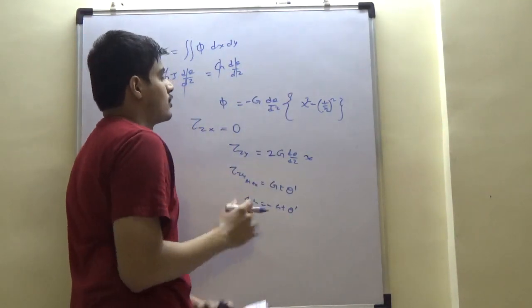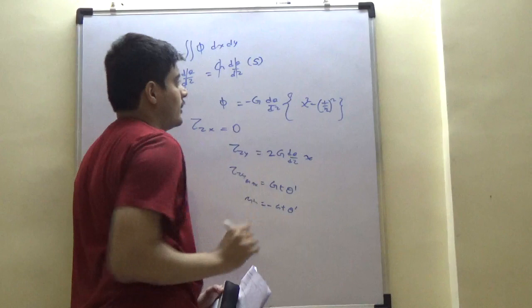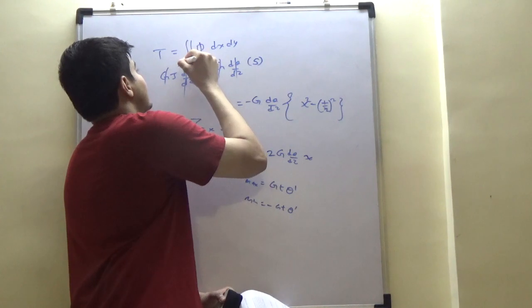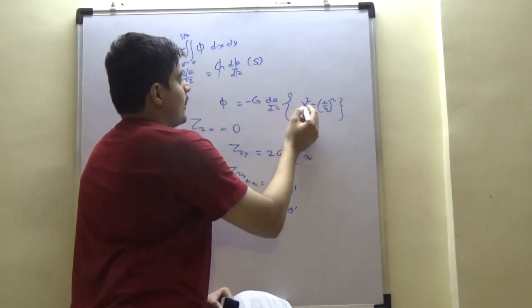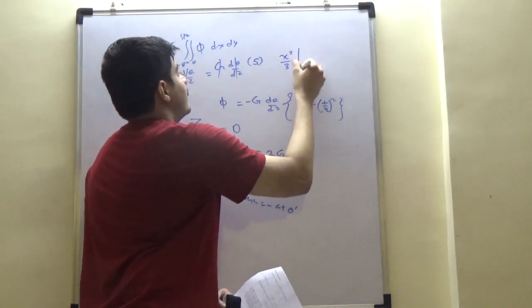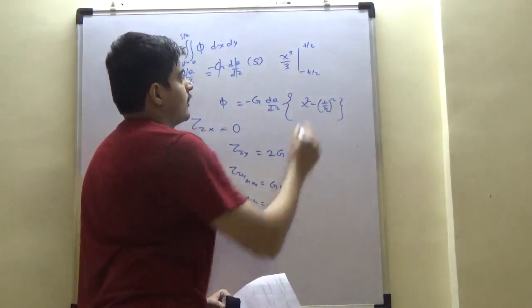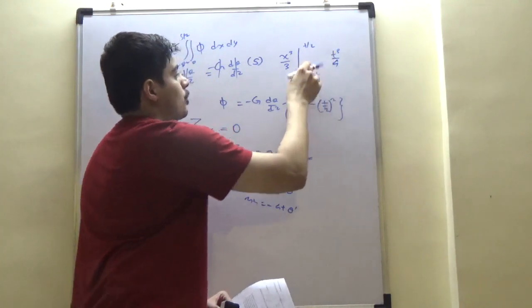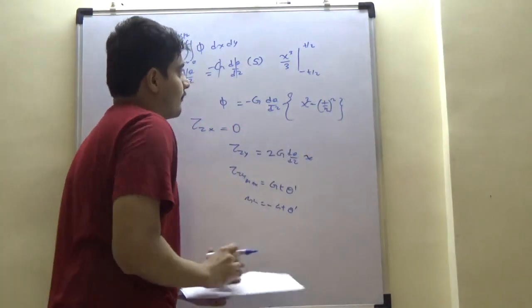dy is invariant, so y is going to go from minus s by 2 to s by 2. So s is going to be here, right? The length, because dy goes from minus s by 2 to plus s by 2. So s has come out anyway. So x square integral is going to be x cube by 3 from minus t by 2 to plus t by 2. I am keeping minus sign here, right? So t cube by 8. So t cube by 4 this will be, because both will get added, a minus b minus a minus b. So t cube by 12, right?